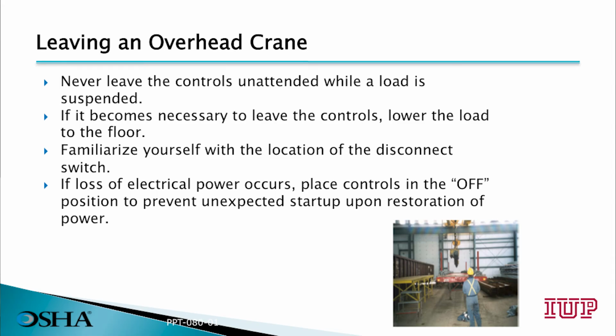If you need to leave a crane, never leave the controls unattended while a load is suspended. If it becomes necessary to leave the controls, lower the load to the floor. Always familiarize yourself with the location of the emergency disconnect switch. If loss of electrical power occurs, place the controls in the off position to prevent the unexpected startup upon restoration of power.